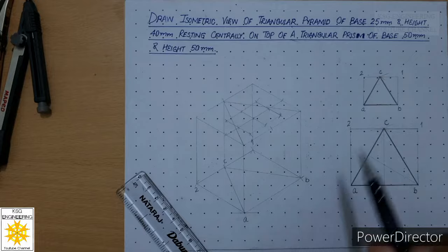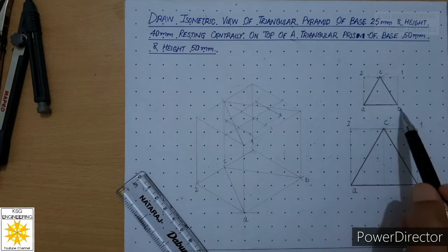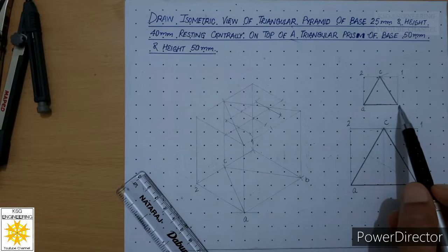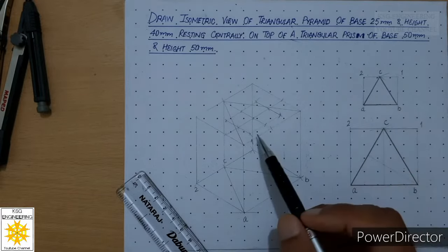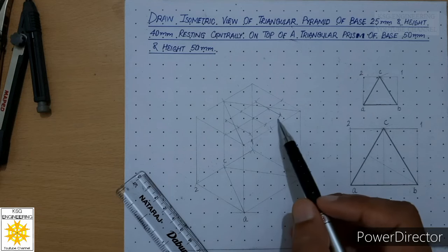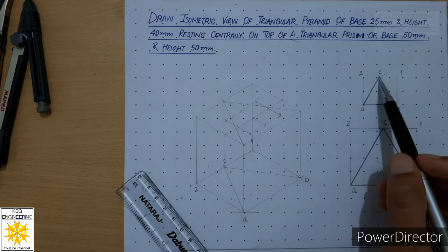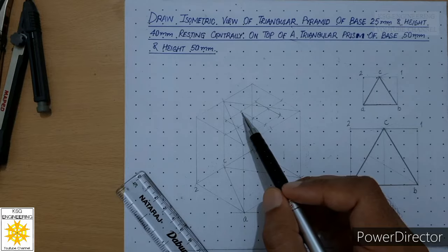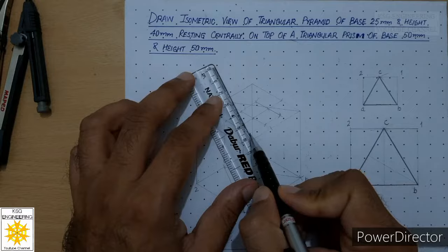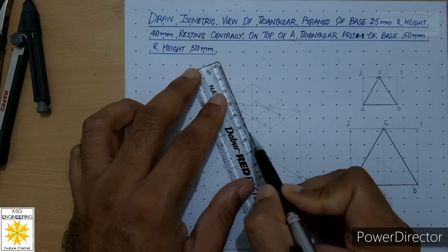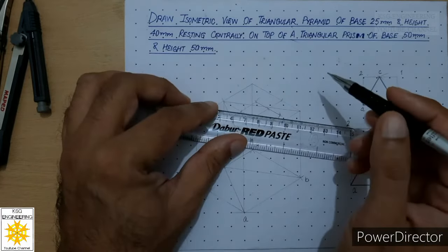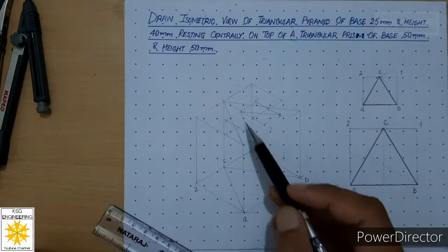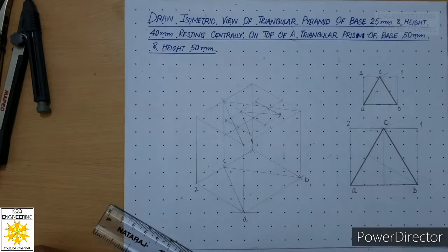Now inside this isometric, we will draw isometric of this triangle. So for that we have to locate these 3 points, A, B, C. You can see these 2 points are shared by triangle and the box. So these 2 points are already located here, A, B. Now we have to locate C, which is at the mid of 1, 2. So mid of 1, 2 is already located. This is C. So we have to connect these points with thin lines. So that will give us isometric of the triangle.